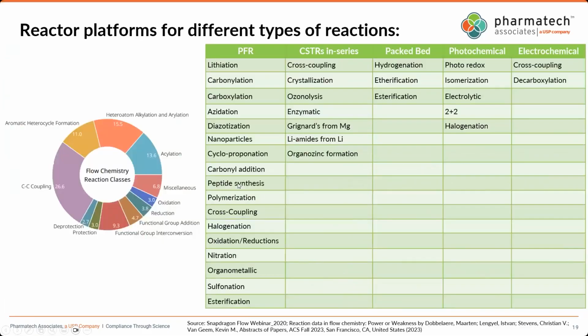No worries. I also think it's important to highlight that not just the pumps, but also the reactors' material selection is one of the big criteria, in characterizing such a reaction system. Yes, absolutely. Because most of the API chemistry involves the use of corrosives, highly basic or acidic conditions. So the choice of the MOC also plays a crucial role in deciding what type of reactors can be used. That's another good point.